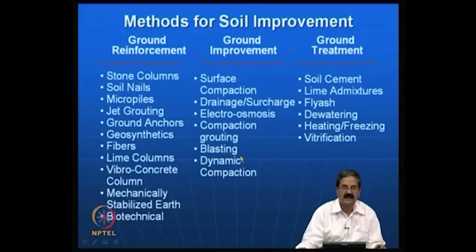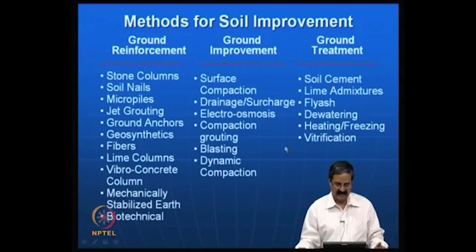Then blasting. Say, for example, we see that the soil is liquefiable. So, how do you see that the liquefaction tendency is reduced? Because we create blasts in the ground. I have seen some cases where, just as you place mines when you want to break rocks, you do blasting. Similar to that, you introduce some charges into the liquefiable deposits and then blast them.